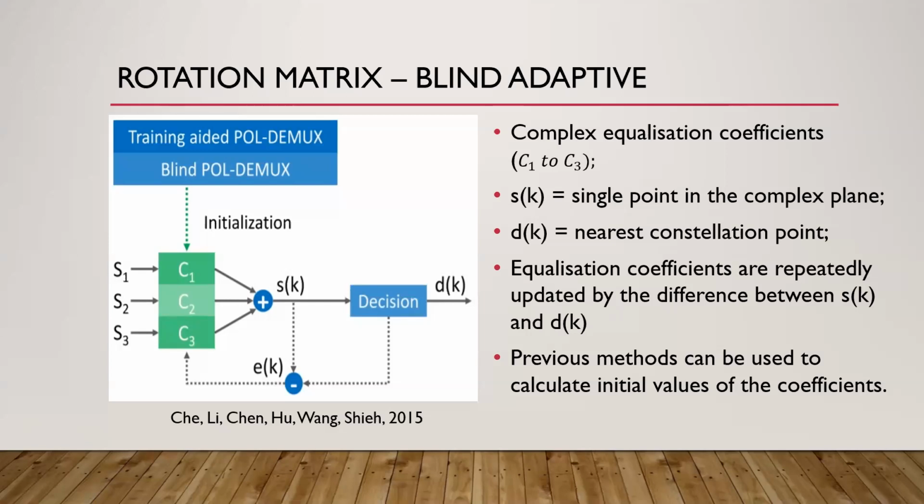So we amend the complex coefficients to what they ought to have been in order to land exactly on the nearest point. If, for example, the resulting point is in the first quadrant, we assume it should have been the 4QAM point in the first quadrant.